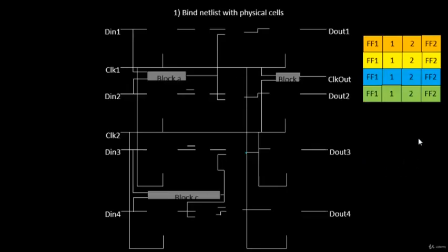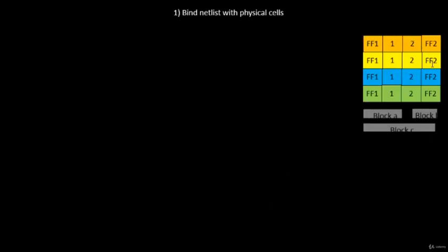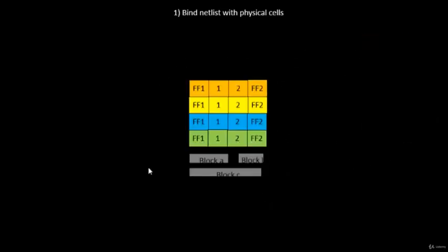Now we'll take these blocks and remove these wires. Let's talk a bit about this particular thing. These things are present in a shelf, and let's call that shelf a library. A library is basically a place where you will find all kinds of books. These are like different books that we have available in the library. Not only this, the library also has the timing information of each gate. For example, what is the delay of this particular gate, and of that gate. All this information is present in a huge set, and it's called a library.